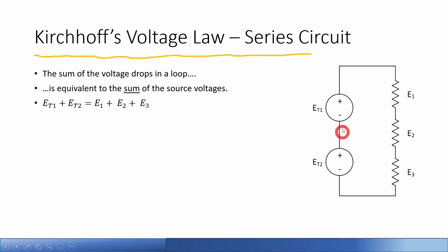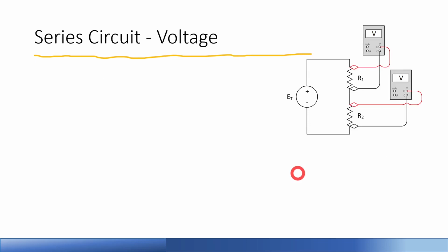So you could think of this as maybe your television remote. You have to put two AAs or AAAs in your television remote, and typically they go in series. Each one of those is 1.5 volts. You put them in series, that would add up. So your remote is going to operate off of 3 volts, and then you have a series of voltage drops in there for the particular circuitry that you have in your remote. So those voltage drops have to equal those two voltage rises.